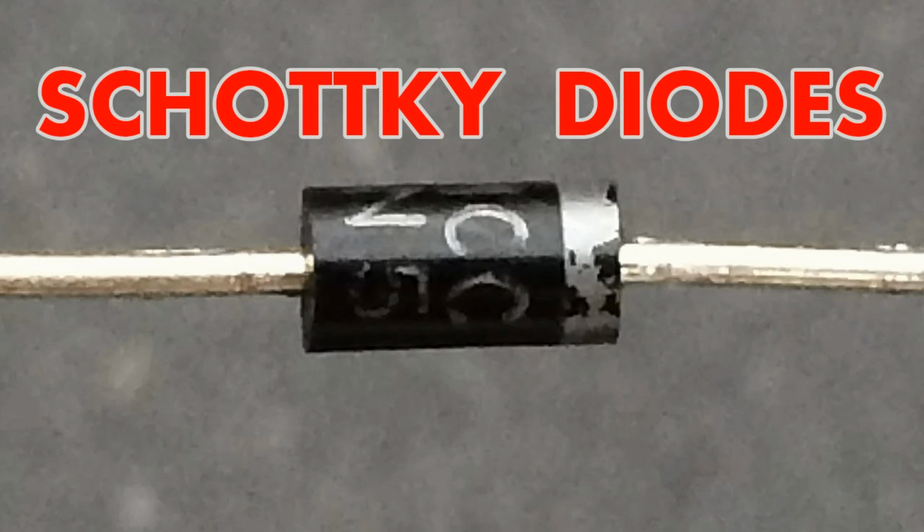The reverse recovery time of a diode is measured from the point where the forward current reduces to zero to the point where the reverse current reaches a specified value, often 10% of the peak reverse current. It is typically expressed in nanoseconds, ns, or microseconds, µs. A shorter reverse recovery time offers several advantages.